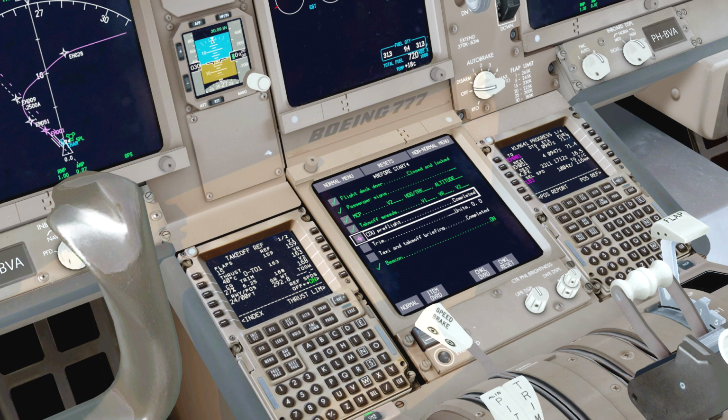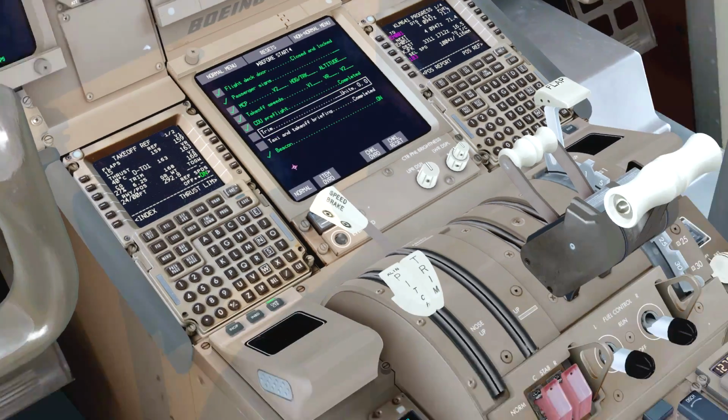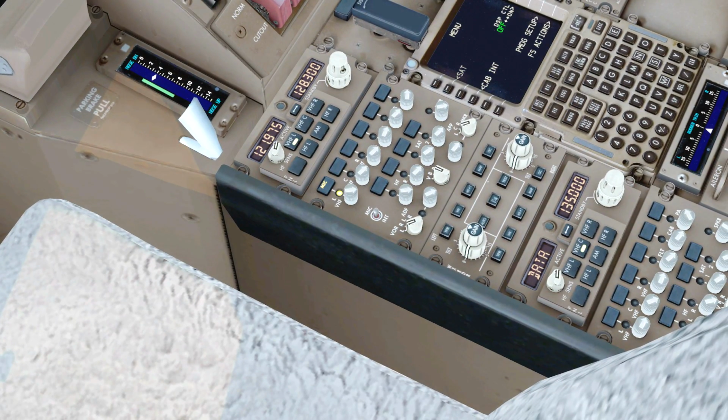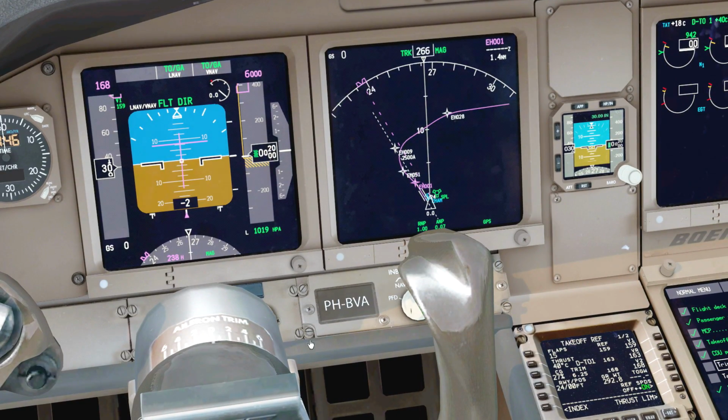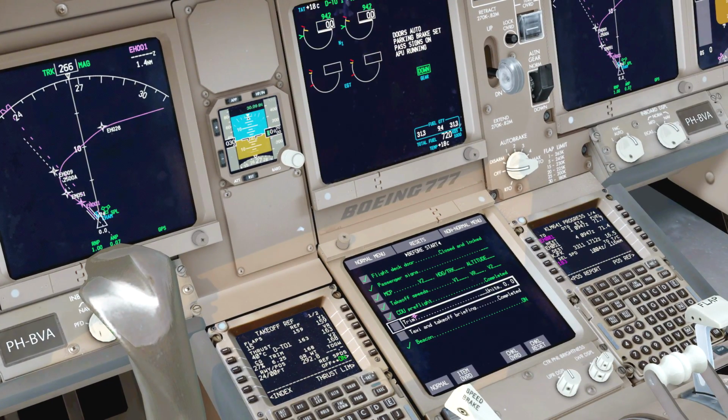All the CDU pre-flight is completed. The trims, you want to make sure that the rudder trim is at 0 and the aileron trim, which you can read right here on the yoke itself, is set at 0. That's all set. We're going to pretend that we did the taxi and takeoff briefing, so that's completed, and the beacon lights are already on. So as you can see, the checklist already check-marks any items that are already finished. Okay, so the beacon lights were already turned on by ourselves, so that already completes the checklist.